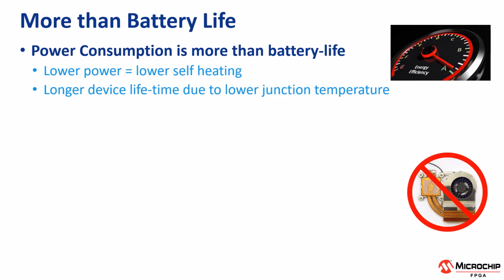Additionally, one of the important aging factors in semiconductors is high temperature. Devices running at higher temperatures will age quicker and reliability of the whole system is reduced. This decreased reliability directly impacts the mean time to failure, or MTTF numbers. MTTF is an important aspect in functional safety.